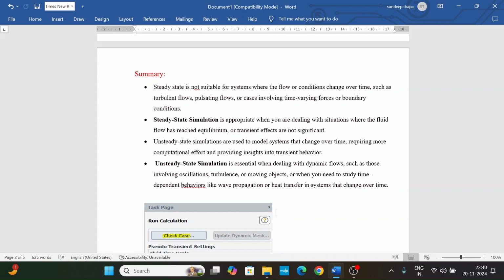Or you just want to see, if we are rotating the drone propeller at 1600 rpm, what thrust that rotation would give you, not with respect to time, but with respect to space, how that thrust force is generated by the drone propeller with respect to space, then you would go for steady state.